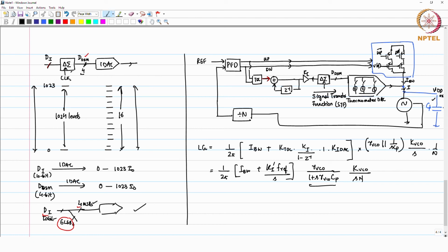So, now I will bring back that we added the ripple bypass capacitor earlier in our regular analog charge pump PLL. In this case, we did not add an extra bypass capacitor, but the parasitic capacitor which exists at the VDD of the oscillator provides you the third pole, and it will help in reducing the ripple because of this proportional path, or because of whatever residual delta I you are going to have from IDAC, it is going to have the ripple there, and it will help in having the ripple bypass.